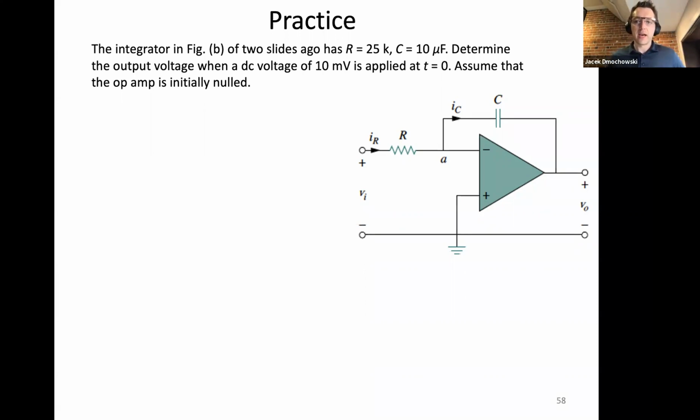And so the way a DC motor works is that the speed of your motor is proportional to your voltage. So if the op amp saturates, then the motor will not be moving at the required speed, for example. And so it is very bad. You want to avoid saturation because the rest of your circuit will not operate as intended.